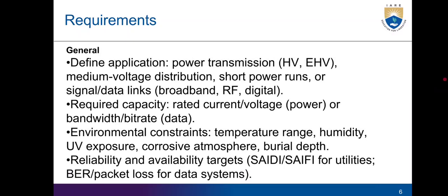Requirements: general. Define the applications: power transmission, HV, EHV, medium voltage distribution, short power runs or signal data links, broadband, RF, digital. Require the capacity: rated current and voltage, power or bandwidth, bit rate.